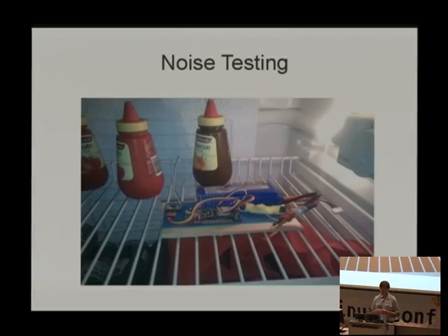So what I did was, first of all, I set the radios with lousy antennas and with minimum power level. 1 dBm is the lowest I could go, so just over 1 milliwatt, 1 point something milliwatt of transmit power. And at first I tried putting the radio inside a fridge. And then I thought, close the fridge, metal all around it, I hoped. Somebody suggested earlier today it might be a plastic fridge. And I found that it still got very, very strong signal.